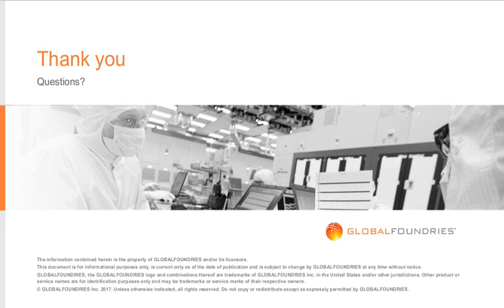Great. And next question, is there a shallow trench isolation between transistors in this technology? Yes, that's also an advantage of SOI. There's shallow trench isolation from device to device, so it can isolate the devices. That can be used in the stack solution to improve the power handling in the switch design. It's especially important in switch design.